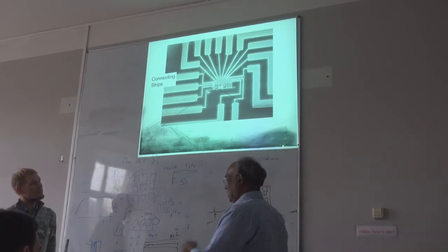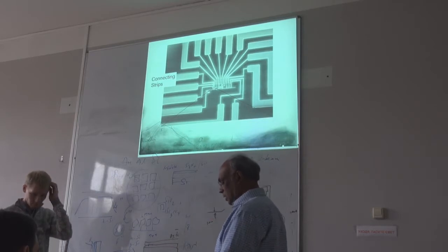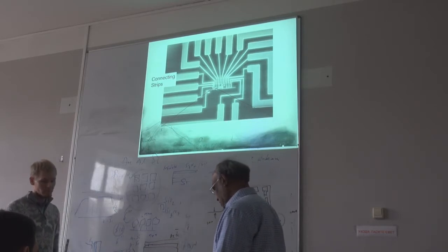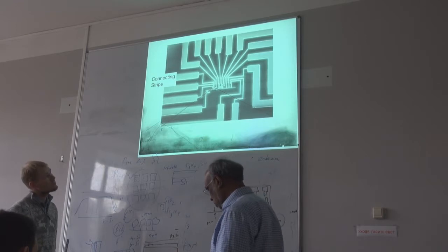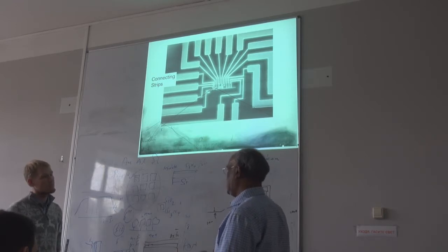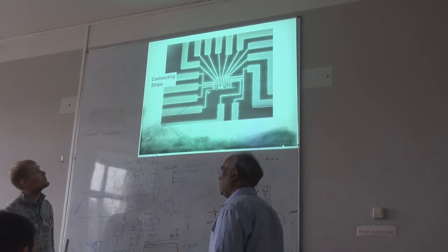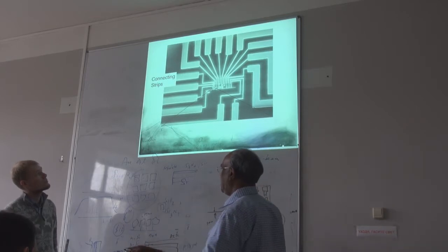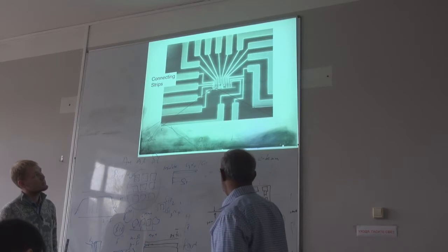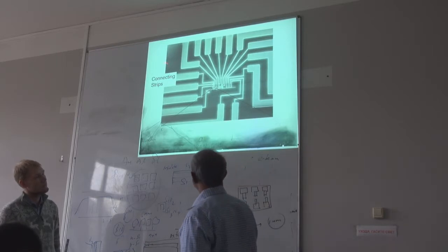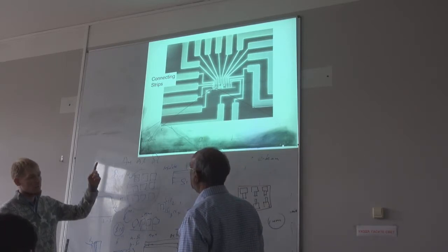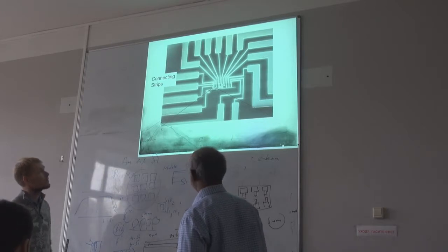Then, the same way, you put your polymer layer, the photoresist, and put the mask, and do the developing, etching, and then deposit gold and release. Then you can get these gold pads here. These are electrodes for measurements.